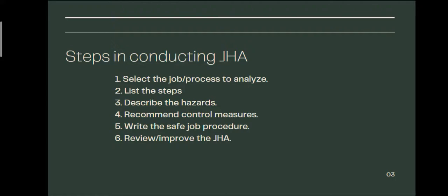Step 3, in describing the hazard, prepare to answer the following. What can go wrong, what are the consequences, how could it happen, what are the contributing factors that influence the hazards, and how likely is it that the hazard will occur.